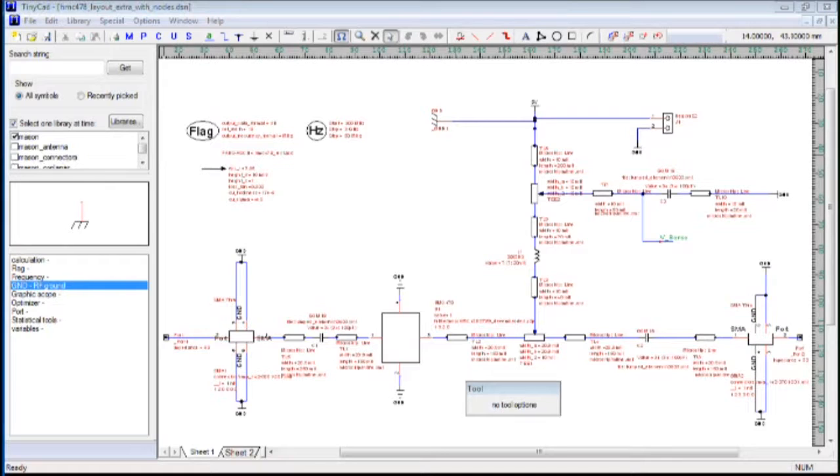Some of our real-world components do not have one-to-one mappings between the actual terminal pins and the S-parameter ports. This is a Hittite amplifier. The manufacturer provides the S-parameter data, the touchstone data, and it also gives us what the footprint is. So I've created a smart footprint. It's file-based. It includes not just the actual physical shape of the footprint, but also how to connect it up. Where they get connected, and the vectors for how to orient the part relative to other parts.